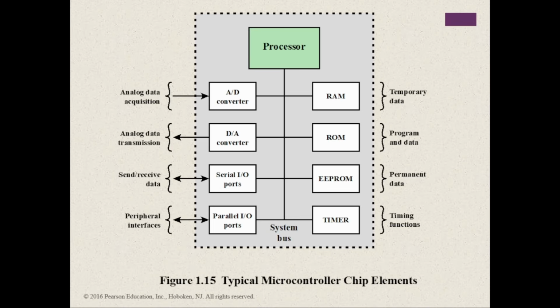Microcontrollers come in a range of physical sizes and processing power. Processors range from 4-bit to 32-bit architectures. Microcontrollers tend to be much slower than microprocessors, typically operating in the megahertz range rather than the gigahertz speeds of microprocessors, because, of course, these only serve a specific purpose. Another typical feature of a microcontroller is that it does not provide for human interaction. The microcontroller is programmed for a specific task, as I've said, embedded in its device, and executes as and when required.